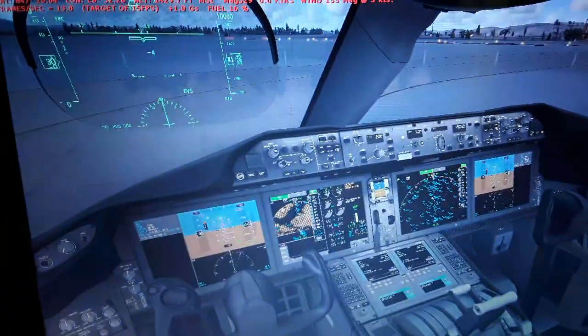It can also calculate whether they climb or descend. We can also calculate with respect to our aircraft, and the closing velocity between our aircraft and the other aircraft. It will give us a warning from the TCAS system, the traffic collision advisory system. It will be displayed in the navigation display.